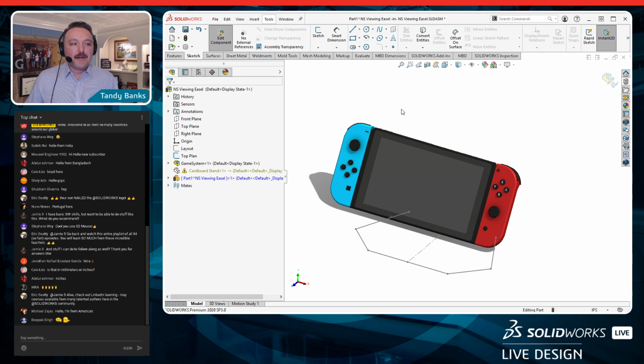Now, something I noticed there, for those of you that are staying really current with the latest versions of SolidWorks: I am running 2020 Service Pack 3. And there's something a little different in Service Pack 3 if you haven't noticed. We used to have a toolbar right up here to the right of our menu bar. And if you'll notice now, that's been docked over here on the left-hand side, where we can now see it, and it stays there active, constant. Those are for things like our new component, save, undo, rebuild, settings, those kinds of things. So a little different change in the UI there if you hadn't noticed that already.